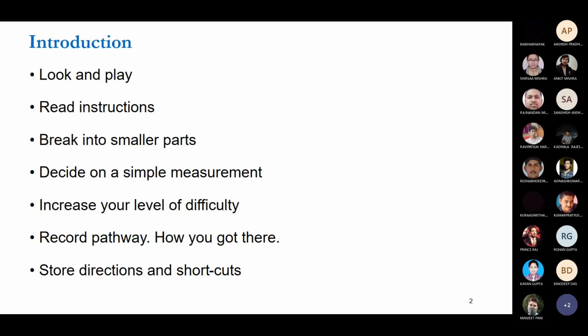But if you want to measure simultaneously, there is another probe, another channel, since I am talking about a two-channel oscilloscope. If you connect the same configuration to other components in the same circuit, then there is a problem. The negative terminal is connected to one element, and the negative terminal of probe 2, channel 2, is connected to another point of your circuit. Then there is a huge common ground problem, and a huge circulating current will flow between the two grounds.